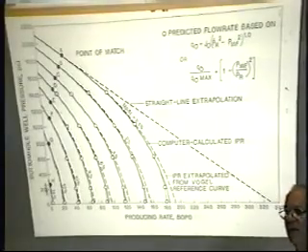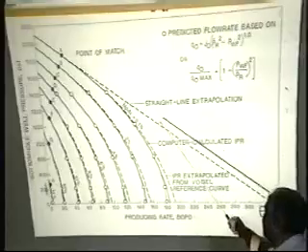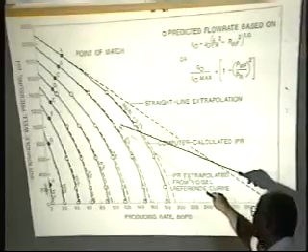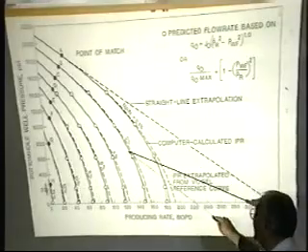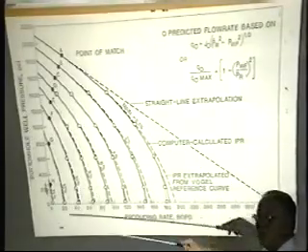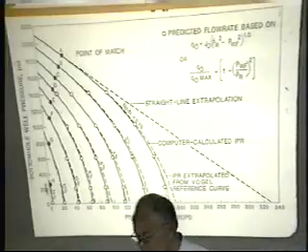So from a production engineering standpoint, there isn't much difference. But again, you also see that at different stages of depletion this curve continues to move. And again, the delta P squared fits all the way. It's a better representation of the inflow performance.